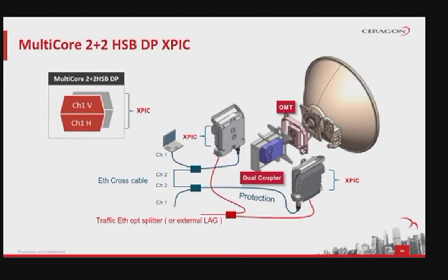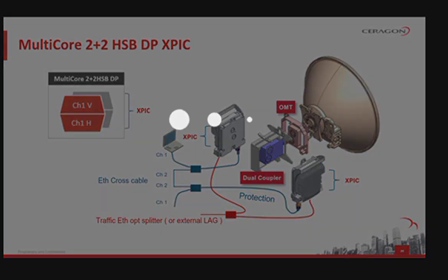For the same 2+2 hot standby configuration but this time using both polarizations and XPIC mechanism, a dual coupler must be used together with an OMT. Remember, the OMT is the device allowing us to operate in both polarizations.